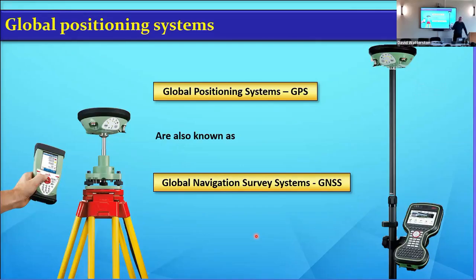If you're digging out material, it's very hard to put material back in, because you would need to compact it down and then leave it for a period. It's easier to dig out stuff if it's too high, but if it's too low, you're stuffed. So anyway, that was a long spiel on GPS. Survey information is quite important.